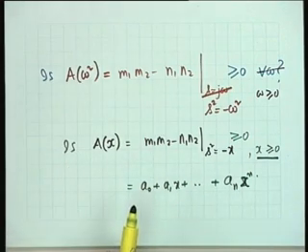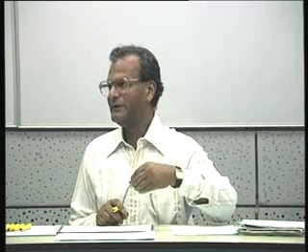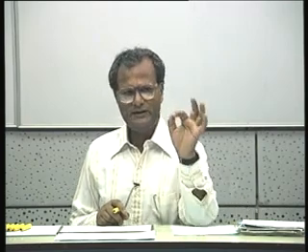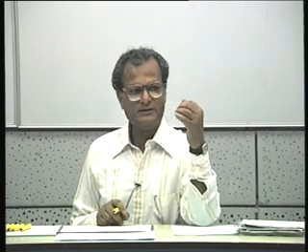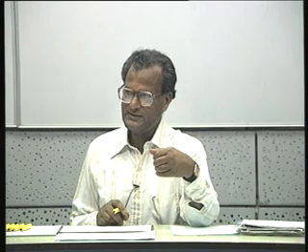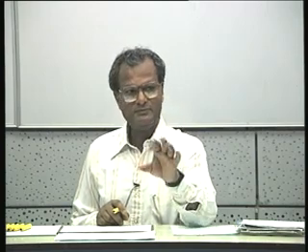You see, from the real part of Z of s non-negative for all values of s in the right half plane, we have come a long way. Only thing we had to check is whether the denominator polynomial was Hurwitz or not. And then we had to test, if it is Hurwitz, does it have poles on the j omega axis? If so, are these poles simple? If these are simple poles, are the residues real and positive? If all the questions are answered in the affirmative, then we come directly to this polynomial, capital A of x. Okay? A long way. Before we subject this to further test, let me ask a question.